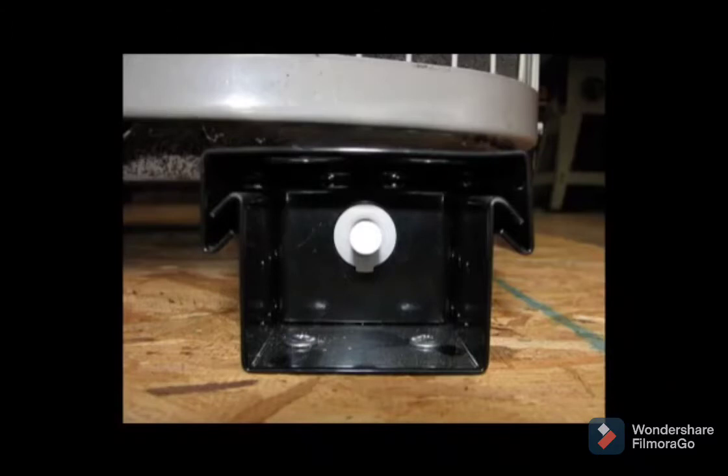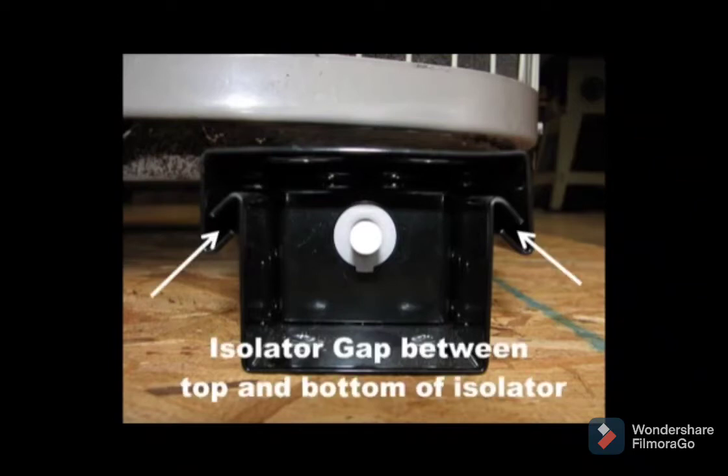For best vibration isolation results, adjustment of the placement of the condenser on the isolators is critical. When the condenser is placed upon the isolators, the tops of the isolators are compressed downwards, separating the top from the bottom and preventing vibration from traveling directly through the metal parts into the mounting surface. In many condensers, however, the center of gravity is not in the center of the cabinet, but is displaced because the compressor is mounted away from the geometric center. This causes the isolator gaps to differ in size, which may affect the performance of the isolator.